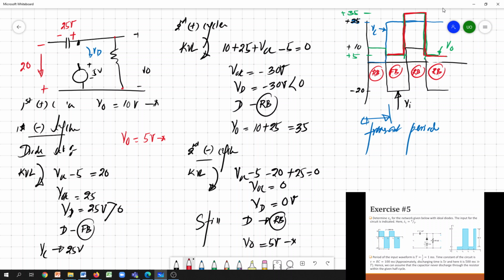So then we can argue that whatever RC circuit appears in the circuit will not allow the capacitor to charge or discharge. Depending on that, we ignore this RC circuit while considering each and every cycle. Then we need to focus on the circuit having the diode.